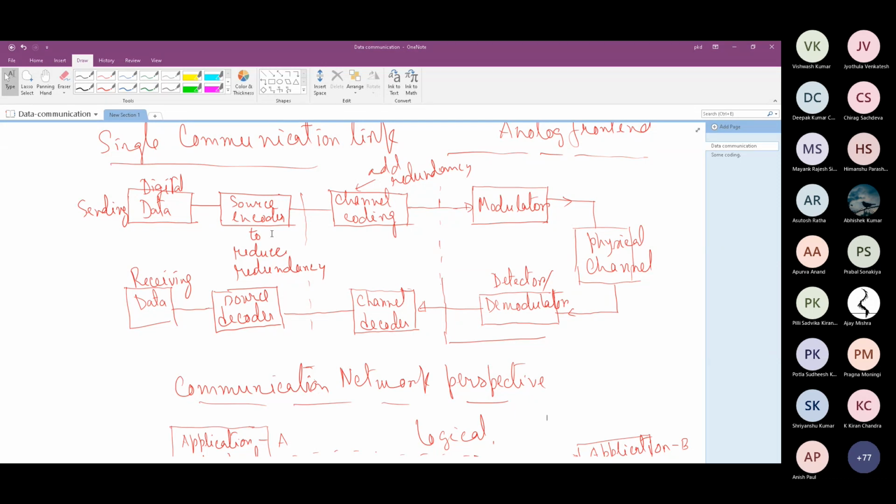So that is in the analog. That part is usually built in along with the analog front end itself. There could be, even in digital, the raw signal. If we want to transmit the raw digital signal instead of using the source coding or channel coding block, the raw digital signals for a short distance can also be transmitted, but then it is usually transmitted with some kind of level shift or kind of coded digital signal.